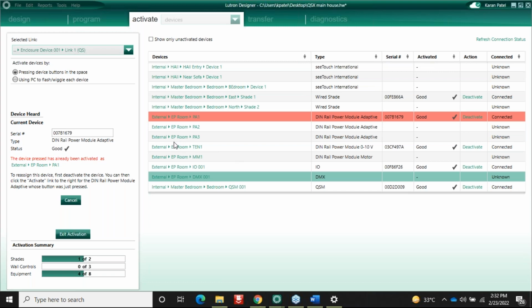So there is a question from Charif: can we extract the programming file from the processor if we lost the file and the cloud services was not activated? No, currently that procedure is not there. Engineering people know how to extract the program from the processor, but that has not been shared with us and not been shared with distributors as well. So currently on all projects, the cloud services must be activated, and the database can be extracted from the cloud directly. So cloud services is required.